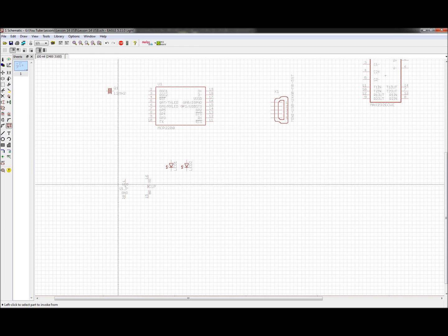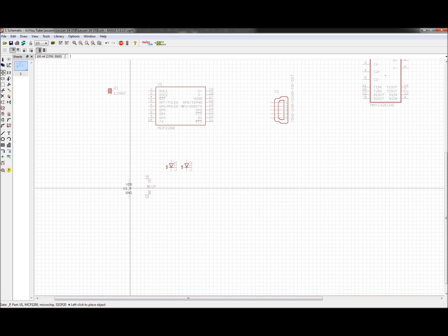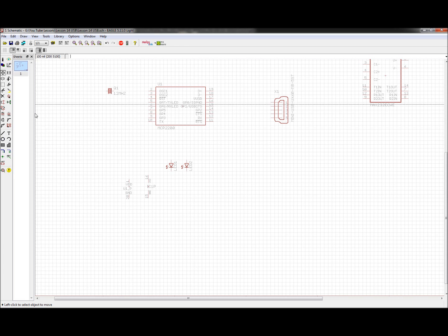In this case, this one is select the tool and then click what part you're going to move or manipulate. The way you move multiple parts is you click on what tool you want to use, so either copy or whatever. In our case, we're going to do move, so we have the move tool selected.